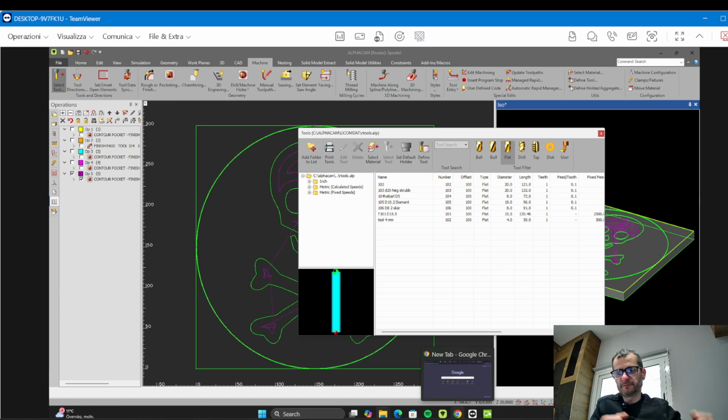So how to put the pieces on the machine, how to set the good position for the vacuum caps. When you have a big panel and the depth can destroy the caps, what to do? To understand how to change a parameter for the tool inside Albatros, how to create a new tool in Albatros, how to create a new tool in AlphaCam. So this is all the procedure where you must touch the machine to understand the good way.